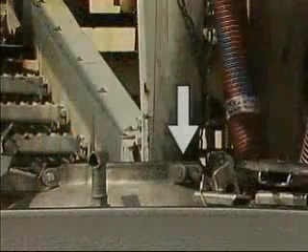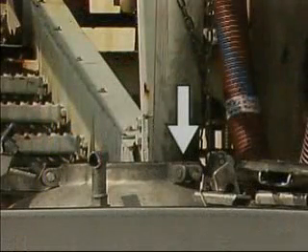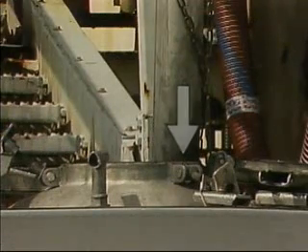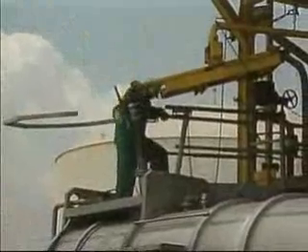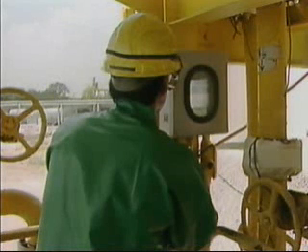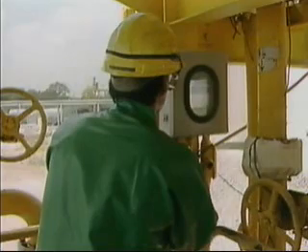The line should be lowered as far as possible into the tank to minimize splashing during loading. The operator then opens the valve on the loading arm and returns to the loading rack. There, he presets a meter for the amount of product to be loaded. This meter is designed to shut off the flow automatically when the desired amount is reached.